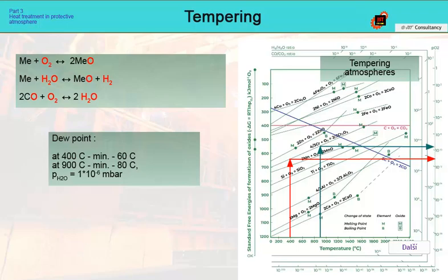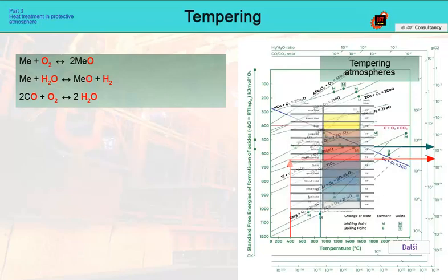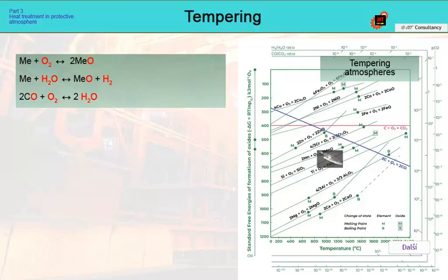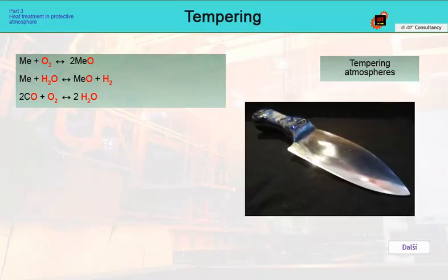In the past, tempering was commonly done according to interference oxide colors. The picture shows, for example, a table of oxide tempering colors published in the past by the steelworks. Today, this method of determining the tempering temperature is no longer used much, but it can still be seen, for example, in the work of artistic blacksmiths or knife makers.